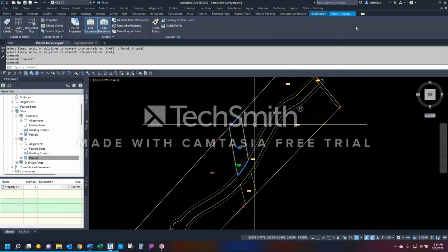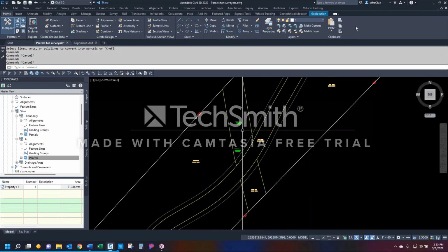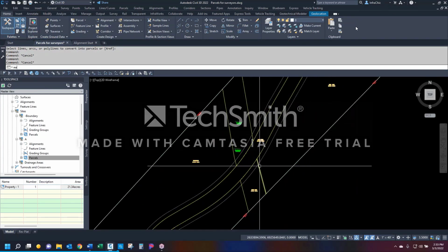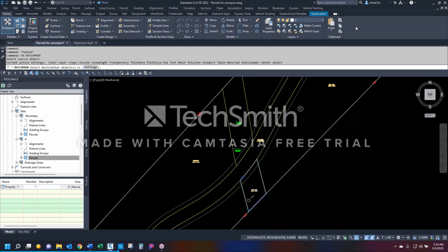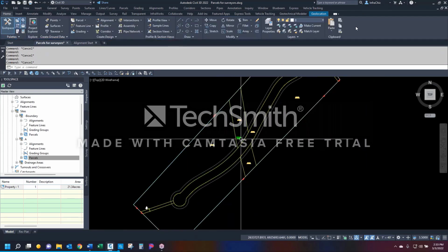That is what was left of the copied parcel to site A, okay? So I can do a match. I want this label to look like that. So MA for match, good old-fashioned match, original origin layer, origin label, destination label. So now it's matched. Note that they all look the same.